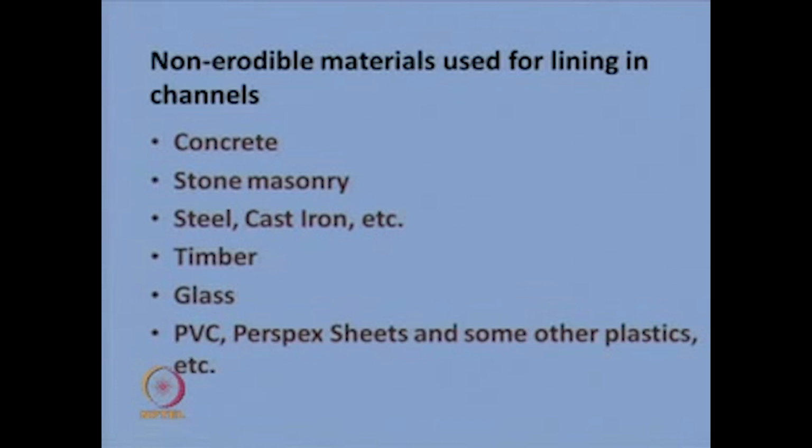So, what are the different materials that are used for lining the channels? Concrete, as you know, is quite strong and does not erode that much. So, concrete is generally used in many channel cross sections as a lining material.